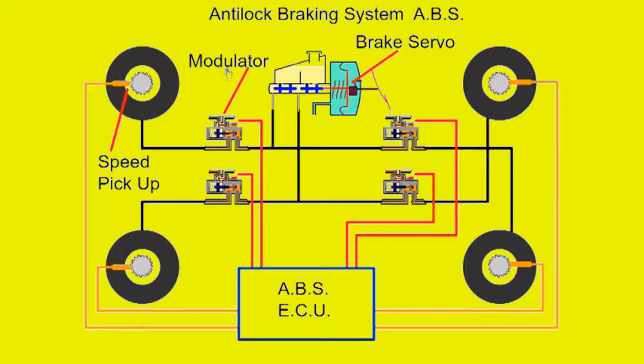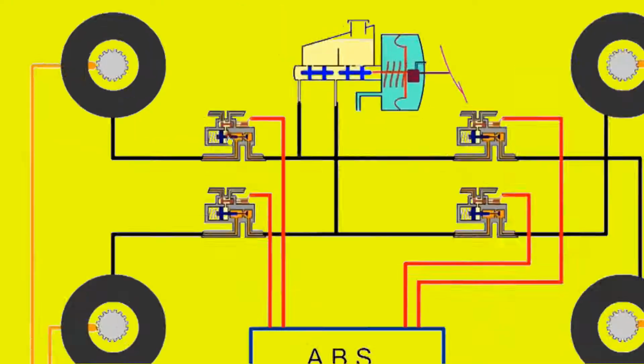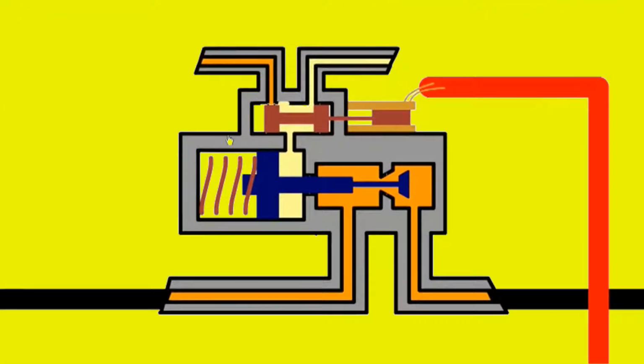Between the master cylinder and wheel is a modulating valve. Imminent wheel lock can be determined by one wheel decelerating at a higher rate than the other 3 wheels, or a wheel decelerating at a rate which is physically not possible without locking up. When the ECU determines that a wheel is on the verge of locking, the ECU activates the modulating valve and releases the brake pressure.